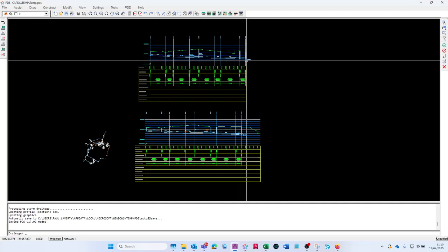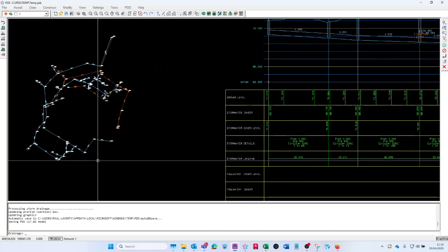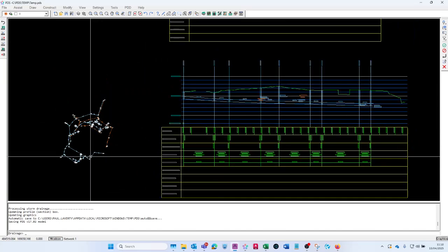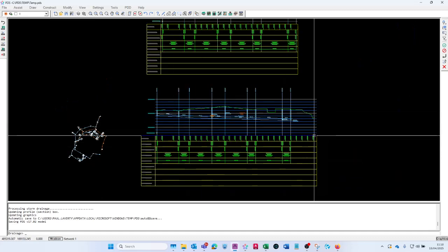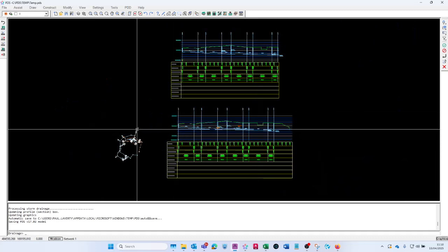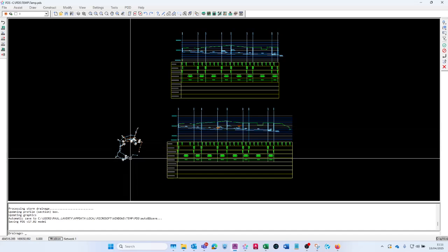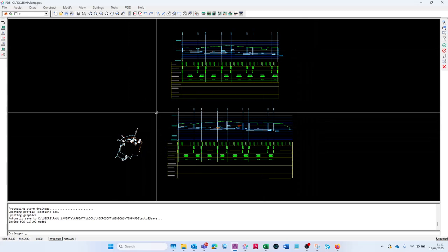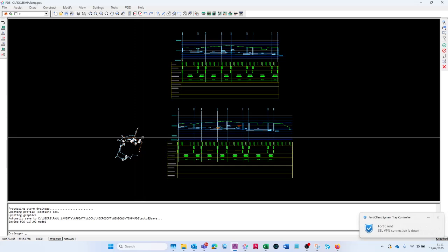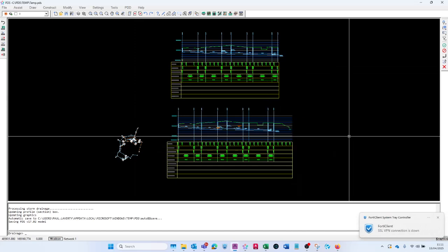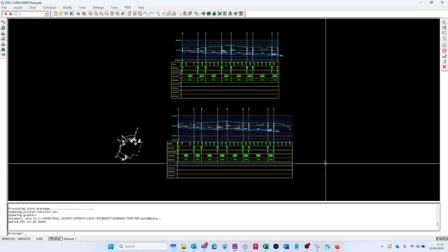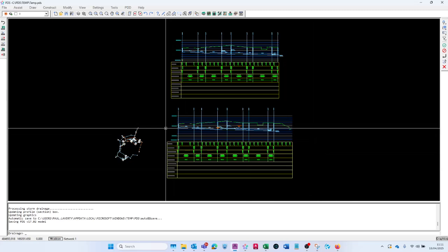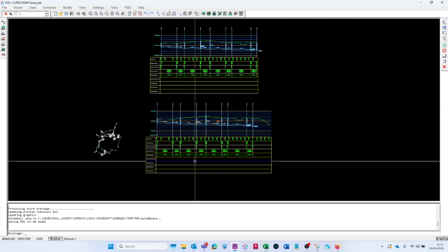There you see, it cut it off at this point. The first time we said go from here to here, but then we chopped off the last couple runs. So it's actually kept the full route as you initially picked. Here we didn't chop anything off, we went from here to here, and it's just kept that route exactly as before. So be careful of adding too many manholes in it and then taking them out. You may end up finding you have a longer profile than you decided to have in the end, and then you'd end up having to chop this off. So just be wary about that. So that's the two profiles.